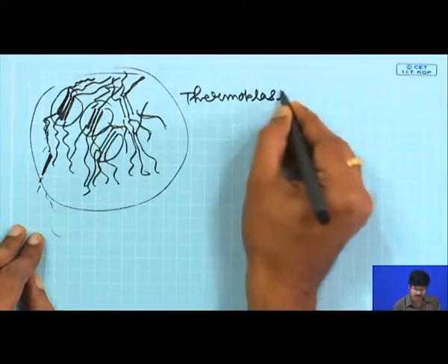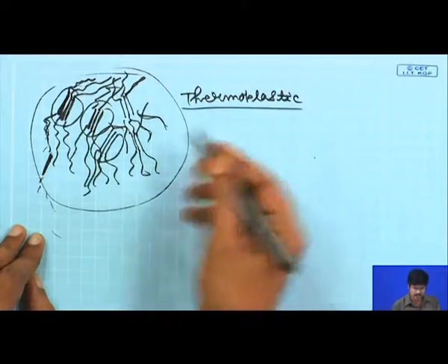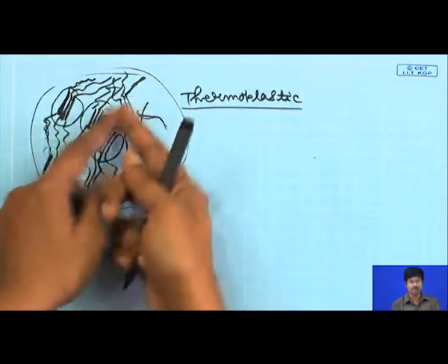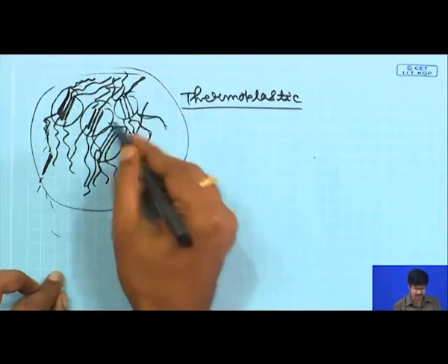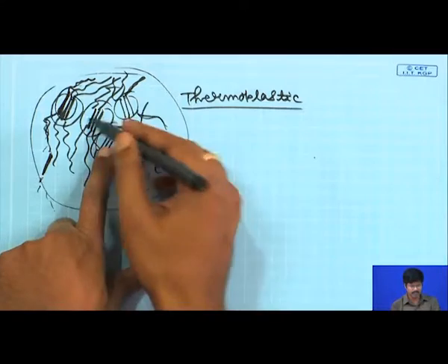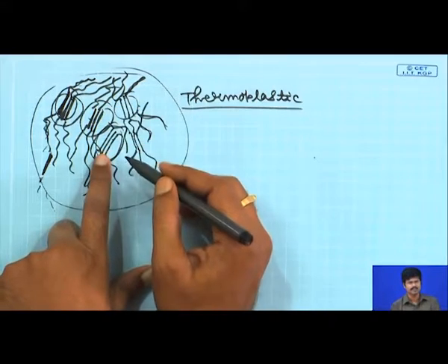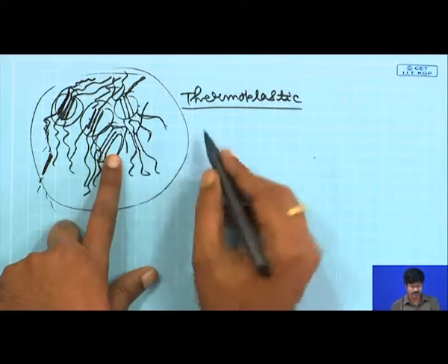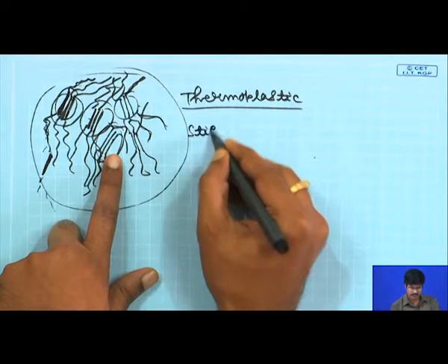because if you heat it up, it will start to flow, and if you cool it down, then again these crystalline domains will appear. Those crystalline domains will provide these cross-linking interactions, and they will give you the stiffness and the strength of the material.